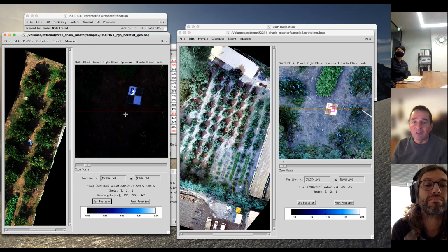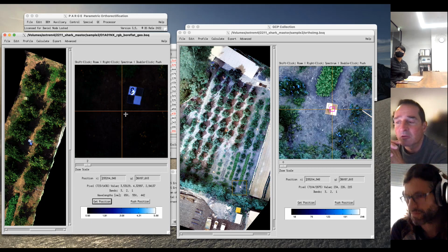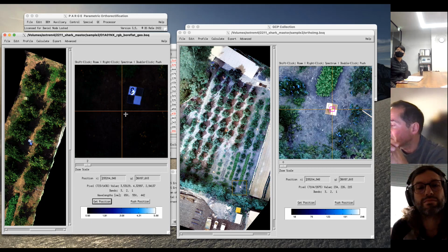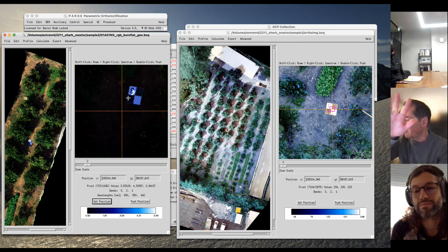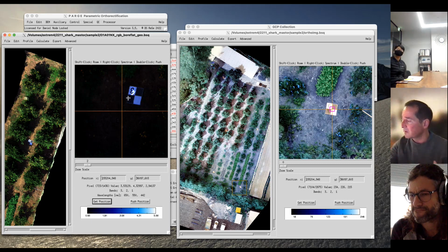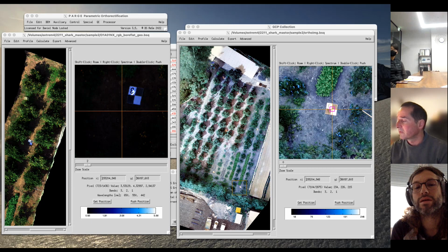So now what could be the reason? I thought, well, how to check this? And then I started to doubt the auto image, if the auto image is really okay. Because it is very uncommon to have an inconsistency like this in the along-track direction, and this should not happen. So what I did, I loaded the auto image into Google Earth to check it against Google Earth.